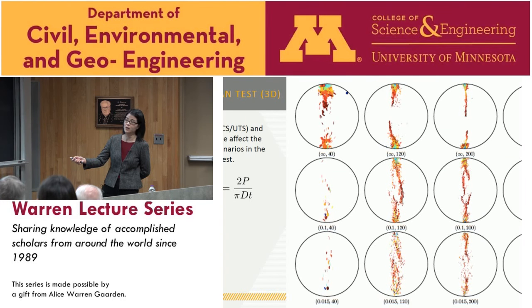If it is infinity, you need nearly infinity force to keep this a constant. And with a very large force, of course, near the loading area you would have failed that area already. And therefore, when you have a large size for the Brazilian test, it's actually not a good idea.